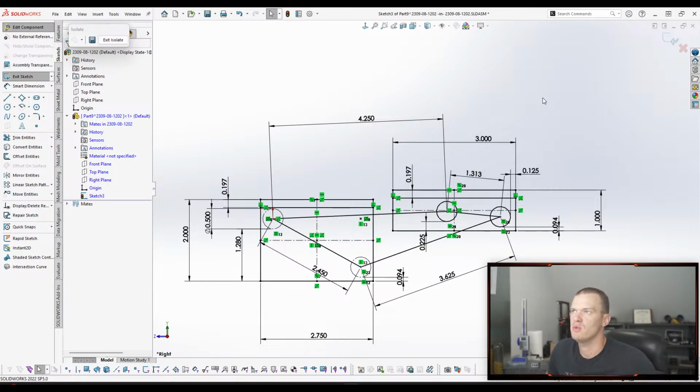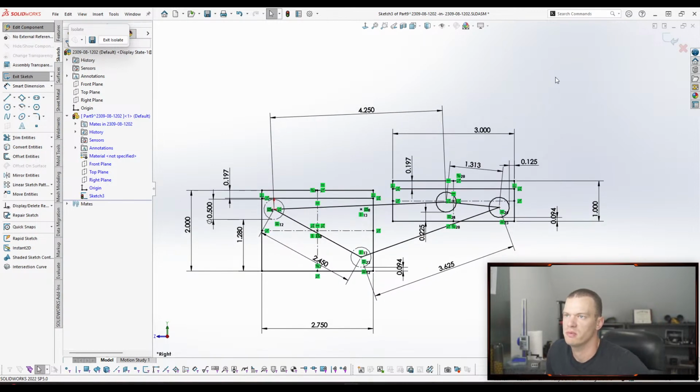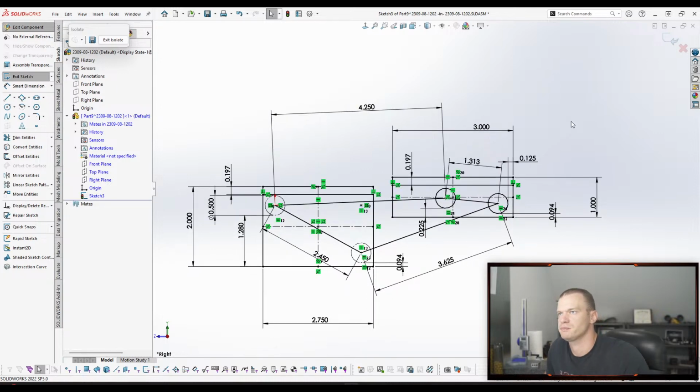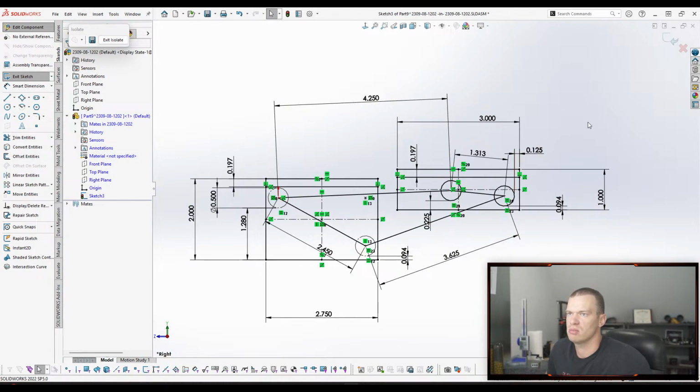And there's a way to remove that in settings. I can't remember what the setting's called, but you can basically stop SolidWorks from automatically creating relationships. So if that is a problem for you, it might be worth it to go in and turn that off. But just something to keep in mind as your sketches become more complex and as you're trying to build relationships, right? Especially the way that I model, a lot of my driving numbers or my driving geometry is relationship based, right?